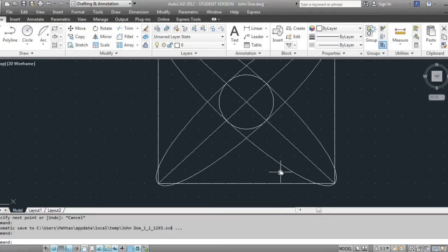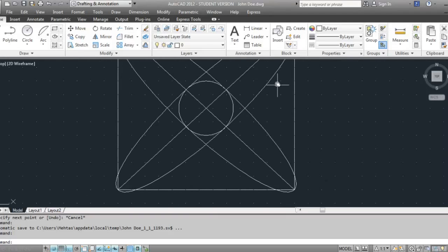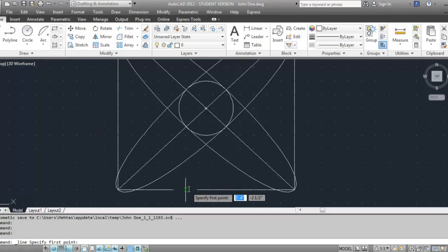Now if you look here very closely, you have 1, 2, 3, well, 4 points here. That amounts to 1/2 inch, 1 inch, and 1.5 inches, and it can go up 3/4 inches because our snaps are set to 1/4 inches. Up here, if you look, you have 1, 2, 3, 4, 5 points, which are going to add up to 2 inches, which is just perfect. So all we're going to do is use the grid and the line command to draw triangles.